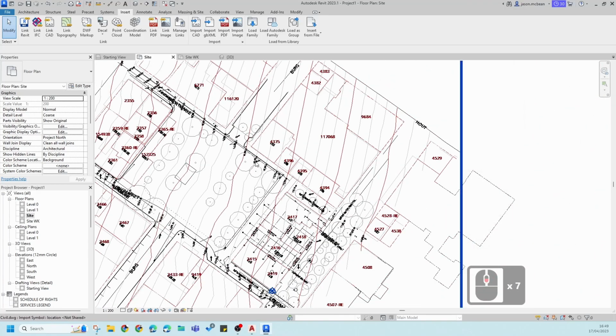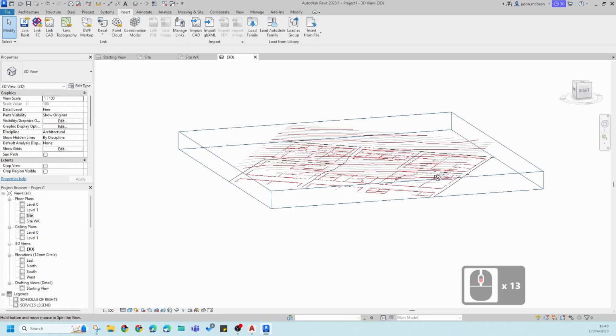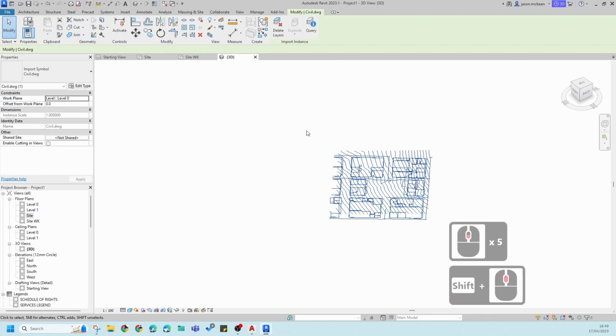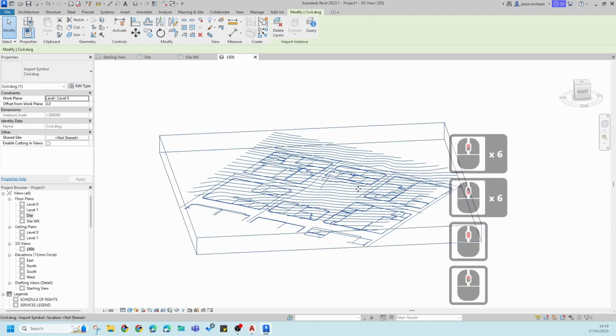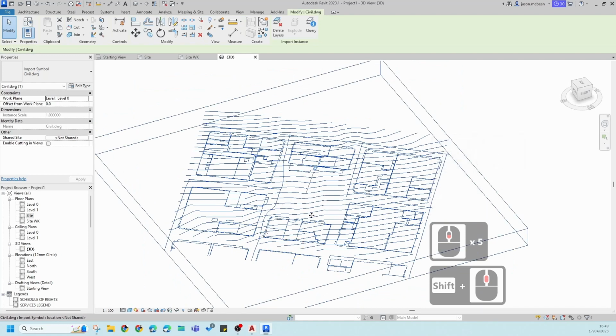Now the difference is when we uncheck that function to bring it in view only, you'll notice that this brings in the AutoCAD file in the 3D view now, whereas that other option to link the file, where it says current view only, doesn't pollute your 3D environment with other unnecessary drawing information. This might be very critical, and I'll explain why we'll need this information.